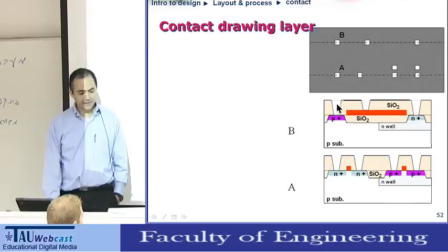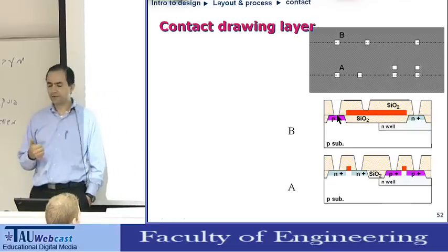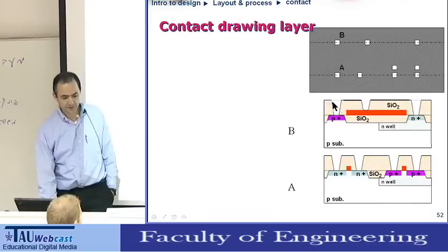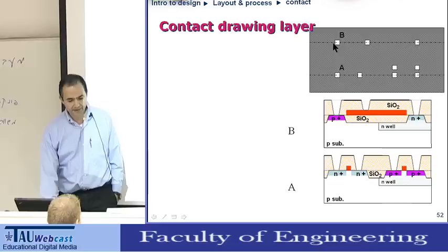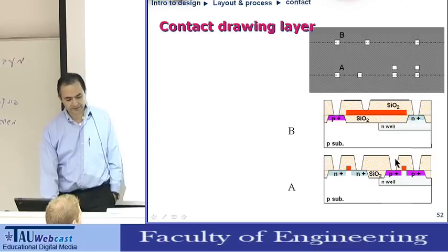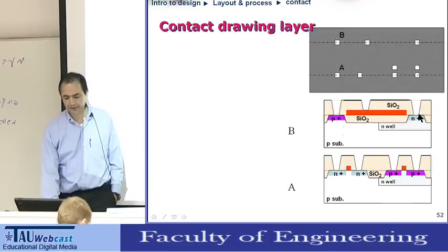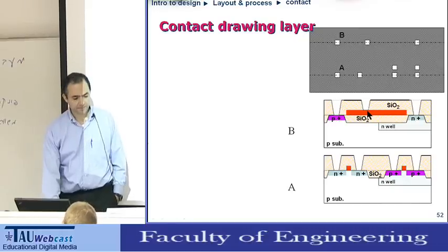The etch will be a dry etch, and we want the etch to be very selective, to consume oxide but not to consume silicon, especially since some of the contacts are deep and some of the contacts are shallower because they need to contact poly. Okay, so you see that we will open, let's see, 9 contacts. Okay, 6 of them for the transistors and 2 for the wells and 1 for the poly itself. This contact will eventually be the V-in, the input.